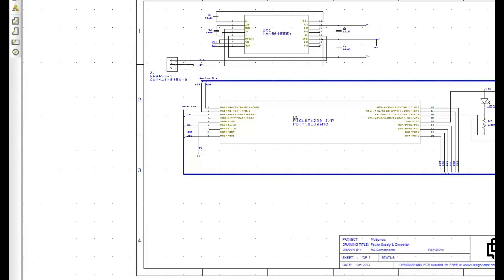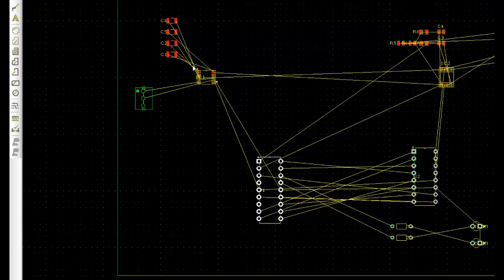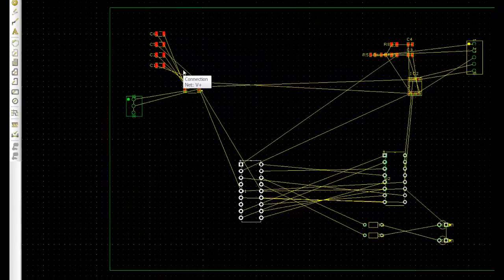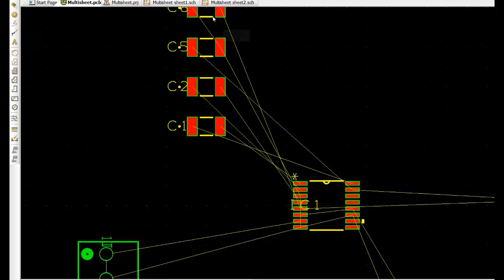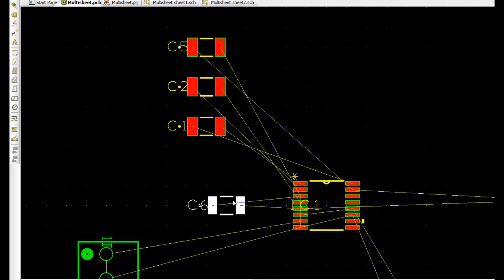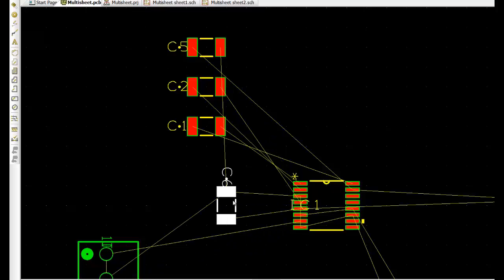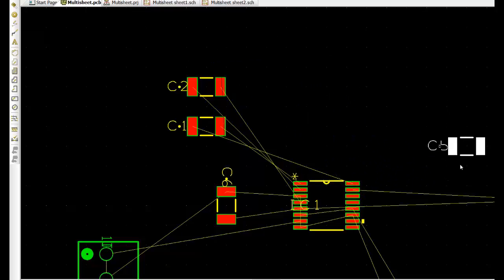First we look at the capacitor associated with IC1. As we move C6 around, we see the interconnections jump between the nearest connection points. We can rotate the component for the best track options, so even though non-polarized, there could be a better orientation for shorter tracks, etc. We repeat this for C5, C1 and C2.